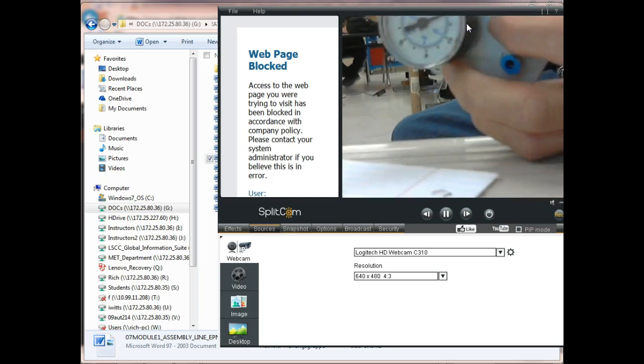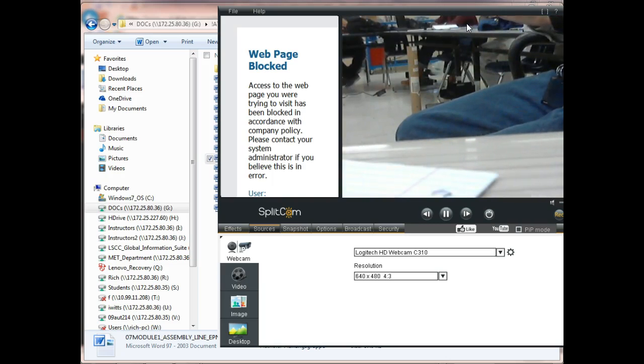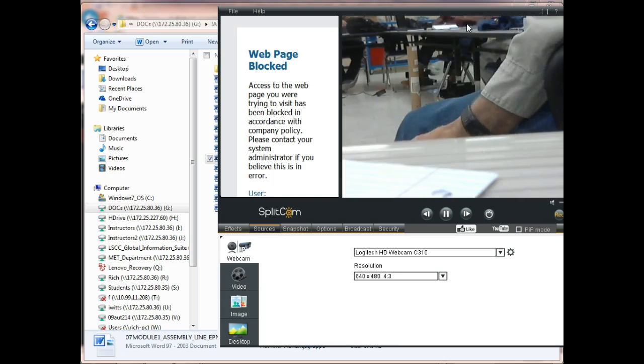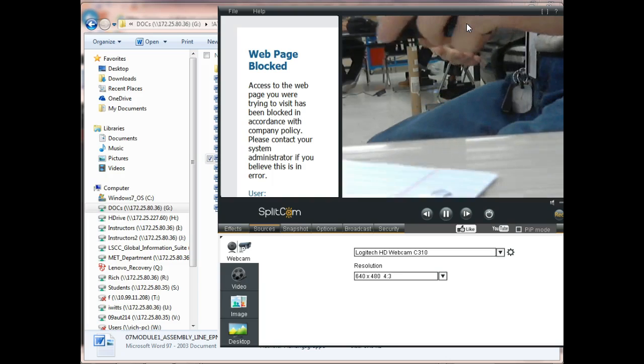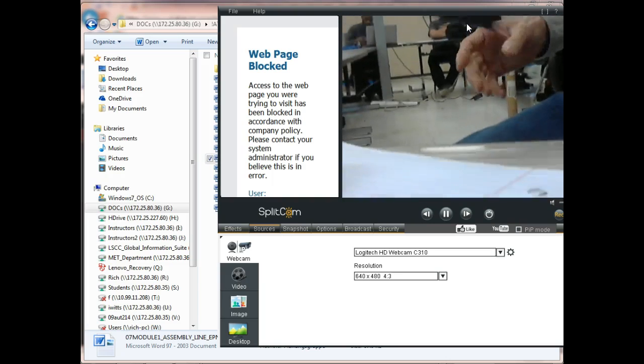Of course, this is a pressure gauge. Unfortunately, we don't have any flow meters, so we teach how to calculate the speed of a cylinder, but we don't have the ability to do it here, because one of the main things you're dealing with is the amount of flow you have. We can't calculate the speed of a cylinder until we know the what? Flow and the area.